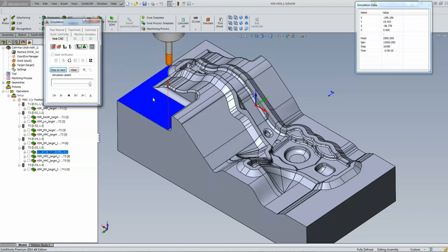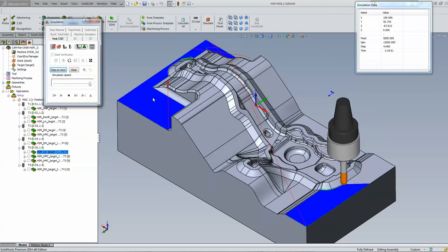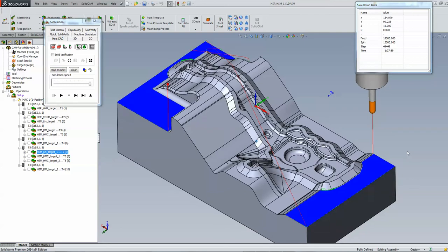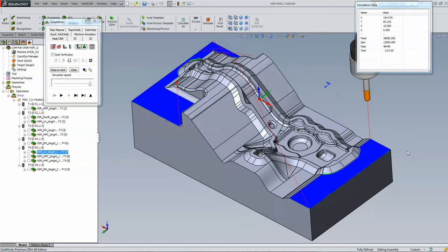Now, the reason that it was done at a 45-degree angle is that there are many people that say, and I've also seen this, that when working for a nice mirror type finish, you're better off working at a 45-degree angle, not exactly either 0 or 90 on the grain of the material itself, but rather this way, and you'll get a nicer finish. Now, again, you can work any way you want to, really. But this is the way we actually found that it worked pretty well with us, and we really got a nice finish. Okay?